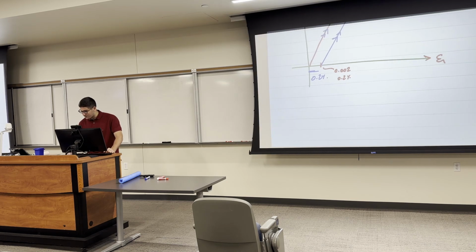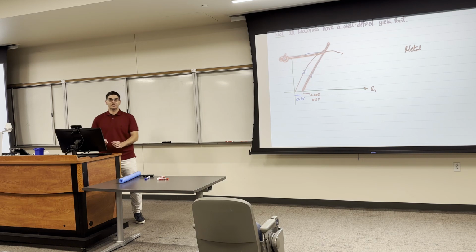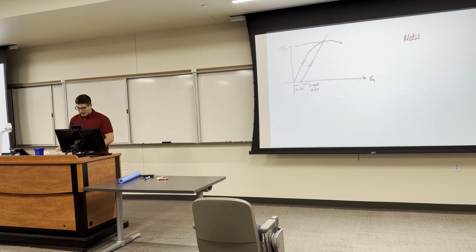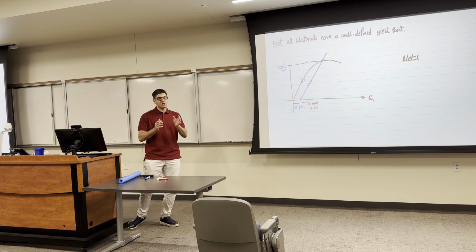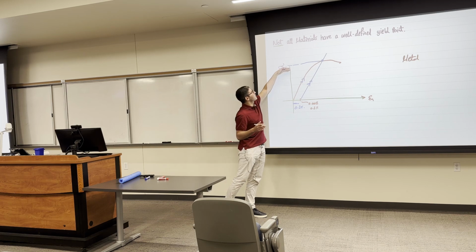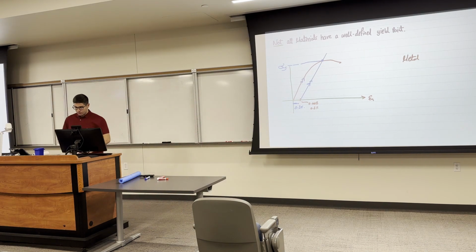Once you detect this point, go with a line parallel to that linear elastic line. And when this line hits the curve, this point is your yield strength. This method we call the offset method, and it's a graphical method. Even with the same graph, students might get different values, but you should all get somewhere in a range. So this is about the yield strength.